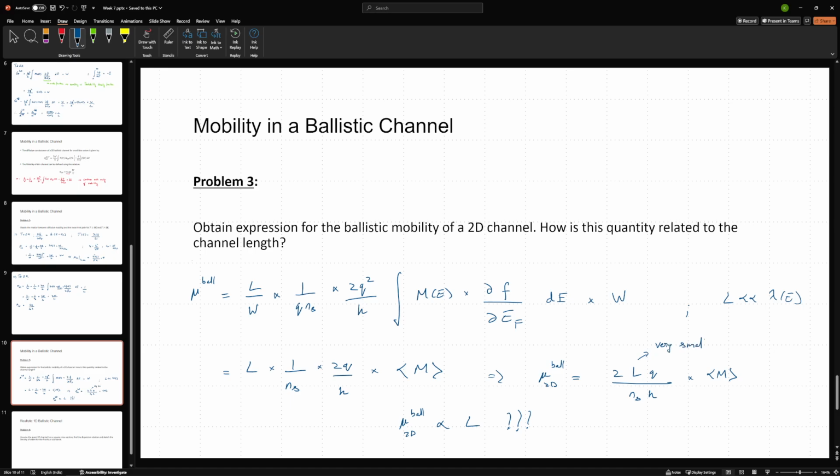Since this is very small, in truth, the ballistic mobility, if you substitute an appropriate channel length where the ballistic limit holds, then you will find that the mobility that you are deriving is more or less comparable to the macroscopic mobility. It will be slightly more, yes, but it is going to be more or less comparable. So that is that for the discussion of mobility and conductance in the Landauer model. Be prepared to look at problems like this, although many of the questions are going to be conceptual. Nonetheless, practice questions along these lines.